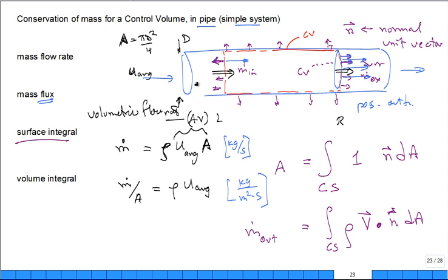So this gives us the right whole thing. So if I compute this and it's equal to 0, then the net inflow is equal to the net outflow. It's no addition or subtraction. If I compute this and it's positive, what does it mean? There's more going out. If it's negative, there's more coming in to the control volume. So that's how you do the surface integral, it's a sum of the fluxes over the area. So it's the net outflow.